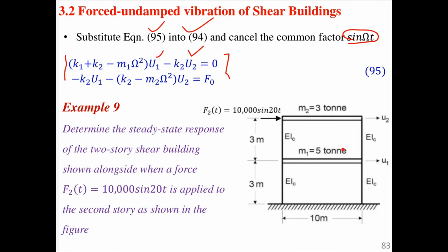If you look at this example, this is the one that we considered in example 8. Only what you have done is to include an externally applied force at the second floor level. Remember, we can also have externally applied force at the first floor level. In structural design 3, when you design with loading, structure and earthquake using, for example, the cantilever method, you know the forces will be acting on the whole of this wall. So usually we resolve them, like we take half of this, from half to half will act at this floor level. Remember, it's acting on a face, the face that is not towards the paper. So we resolve. For example, if this was a new DL, we make it a concentrated load at the floor level.